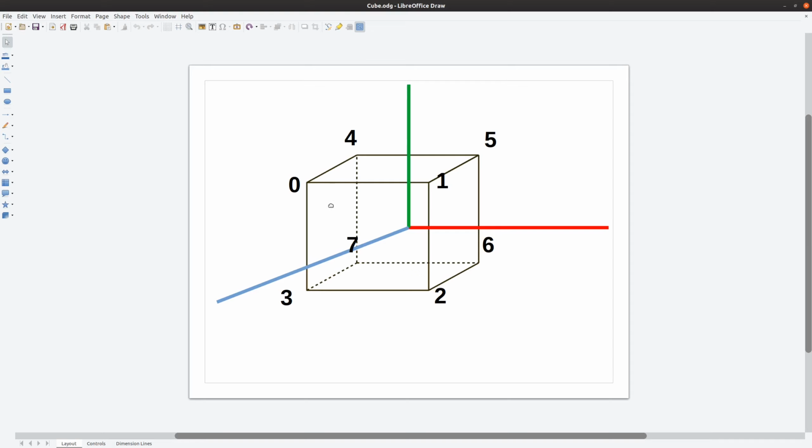So again, if you look at this left face, the way this drawing's going, you would think 0, 4, 7 would be clockwise, but it's not, because we're defining it from looking outside the cube. You have to imagine you're sitting over here. And if you did that, you would want to do 4, 0, 7, because from that point of view, that's a clockwise rotation. I know that sounds difficult.